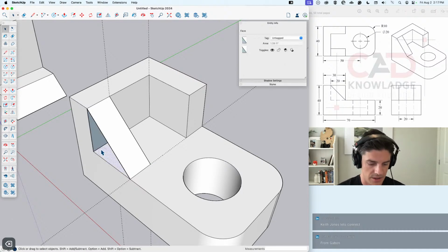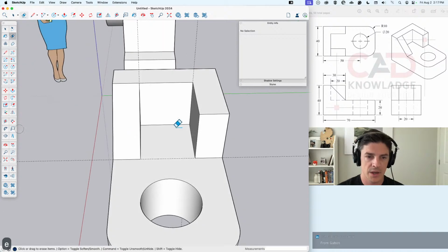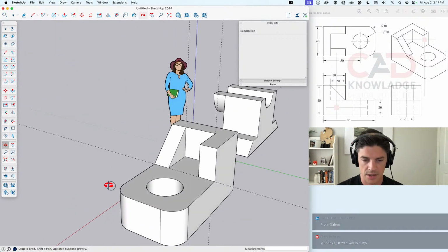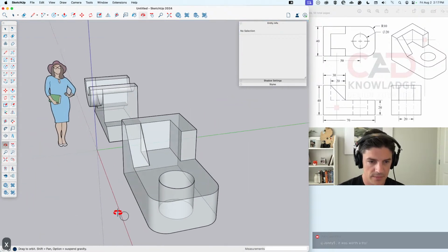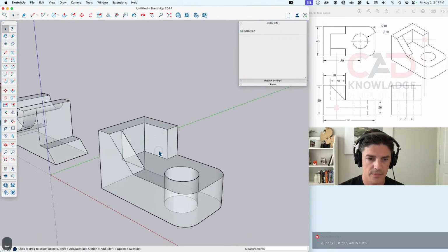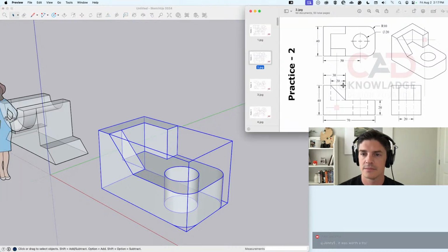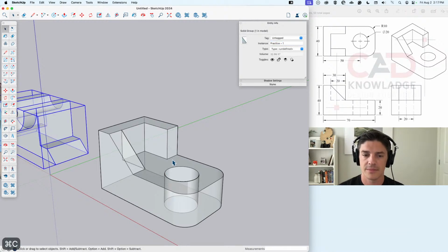So to make a solid, there has to be no internal faces too. That's why I'm cleaning those little guys up. And then I think everything else is fine. Sometimes I have a keyboard shortcut for X-ray mode, which helps me really quickly look, because you never know when there's something in there that you forgot was in there because you offset or because you copied a line somewhere. But using guides, I think maybe is a good way to avoid those extra divide lines or temp lines that I might draw.